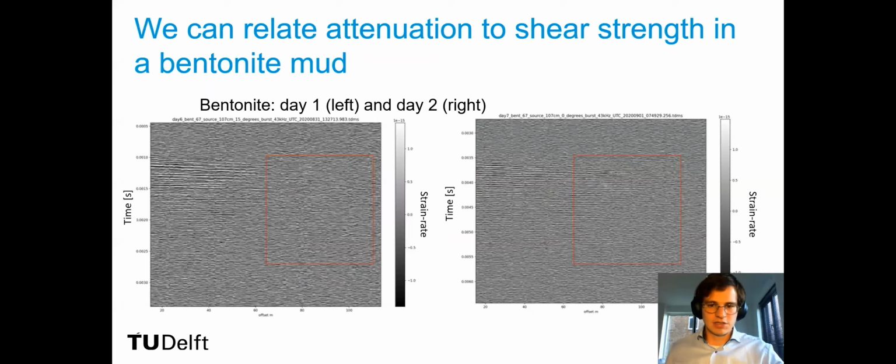So basically, using these guided waves, we can come up with different practical applications. The first application I'm going to show you is seismic inversion using the dispersion properties of the guided waves. For each microseismic event, we can calculate the dispersion image and make a dispersion measurement by picking the peak on the dispersion image, and then we can obtain a stable measurement by compiling dispersion measurements from multiple events.